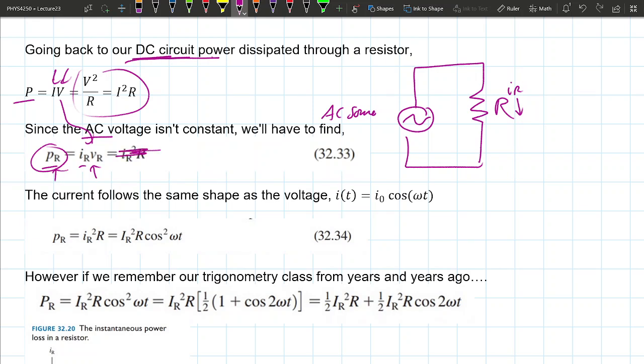We don't have to really worry about the stuff on the right. Actually, you do. Let's just convert this using Ohm's law. You can change this to basically I squared times R, just like up here. Because V equals IR in this case, so lowercase v equals lowercase i times R. R is a constant; once you plug your resistor in, it doesn't change. You plug this in here, then you get I squared times R will give you the power also.